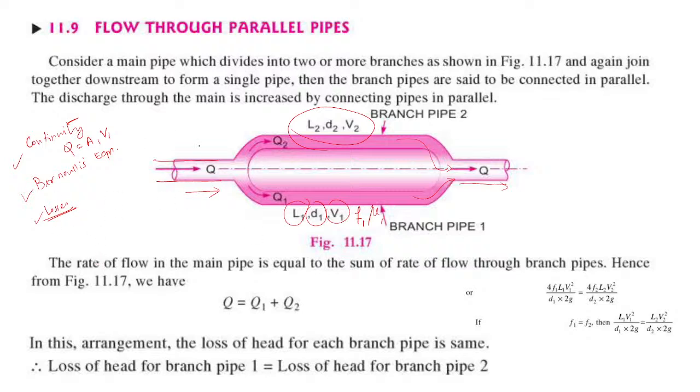Now moving forward, how can we solve this? The major objective of this problem is to find the head losses or some other losses. As you know already from the continuity equation, if this is the scenario and this is a fluid, of course Q is going to be Q1 plus Q2, isn't it? If I say Qi is the inlet and Qe is the exit, then Qi equals Q1 plus Q2 equals Qe. I hope you believe in this, because it works on the continuity equation, and the same thing has been mentioned over here.